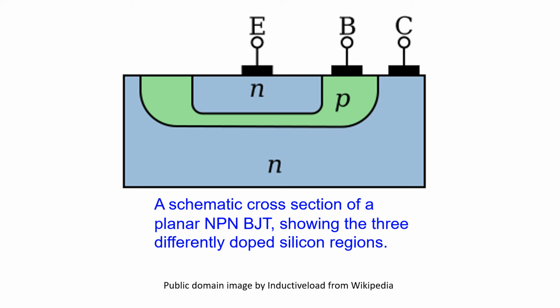These two types are made by mixing small amounts of other materials into the silicon chip by a process known as doping. There is difference in the amount of doping between various layers of NPN and PNP transistors. Emitter is heavily doped compared to other two layers. Collector is typically doped 10 times lighter than the base.